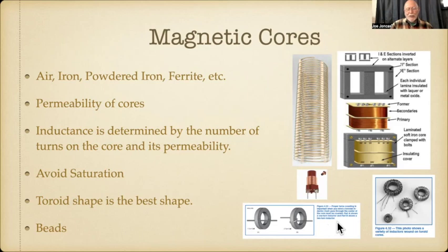In other words, if you have a dipole antenna, which is a balanced surface, that area that you're working in, and then you go to coax, which is unbalanced, the balun helps make it match properly. And with that, you end up with less current, less RF going down the outside of the coaxial wire.